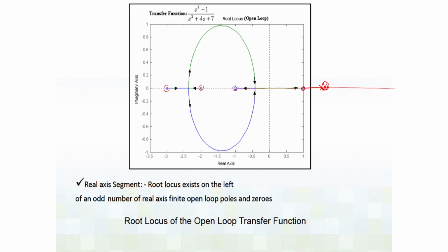The same thing is true for this zero, this pole and this pole, because they are all directly coming here. You remember we always measure the phase angle from this direction, the real axis, to wherever we are going, because this test point is here.